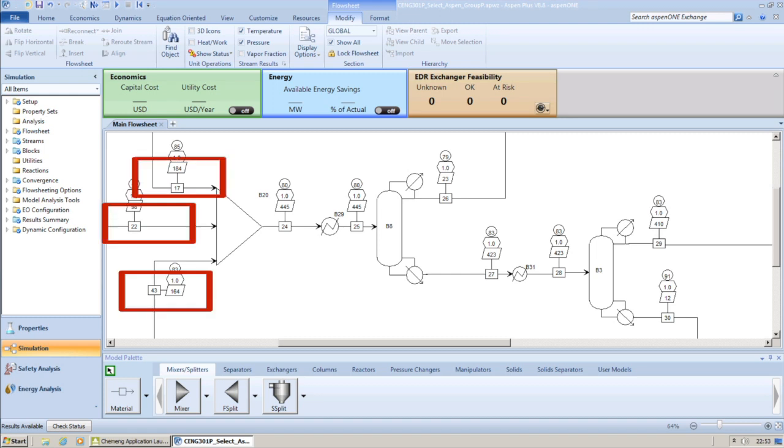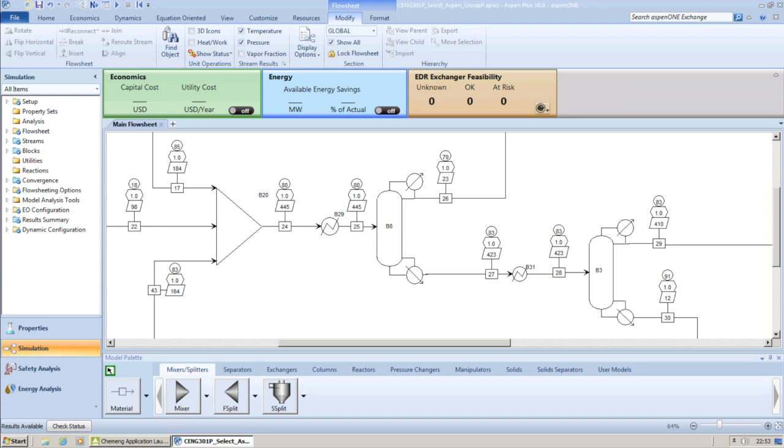After mixing the products from direct chlorination, oxychlorination, and the EDC recycle stream from VCM purification, we can purify the EDC mixture. The first column separates light products from the EDC, and this operates at 79 degrees Celsius at the top and 83 degrees Celsius at the bottom. The second column separates EDC from heavy products such as water. This operates at 83 degrees Celsius at the top and 91 degrees Celsius at the bottom. All reboilers and condensers for columns operate at 1 bar.